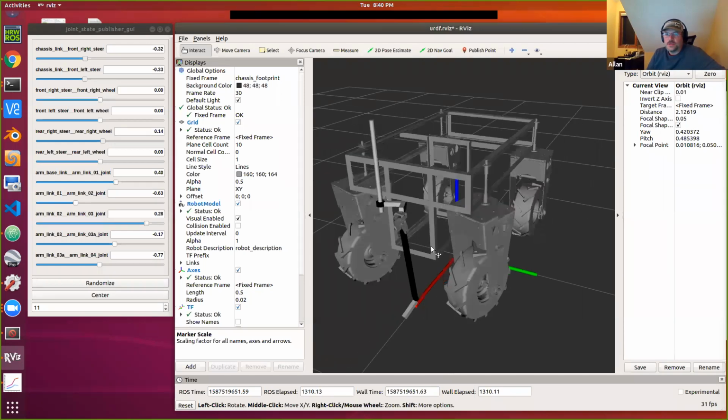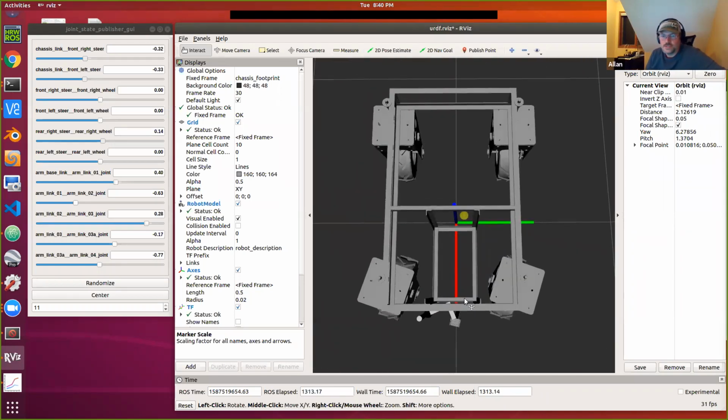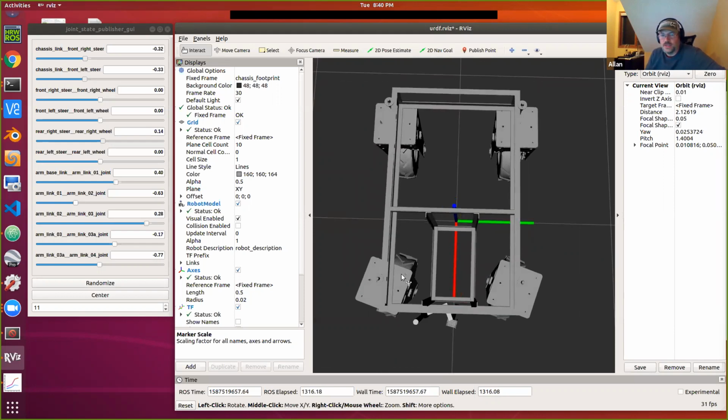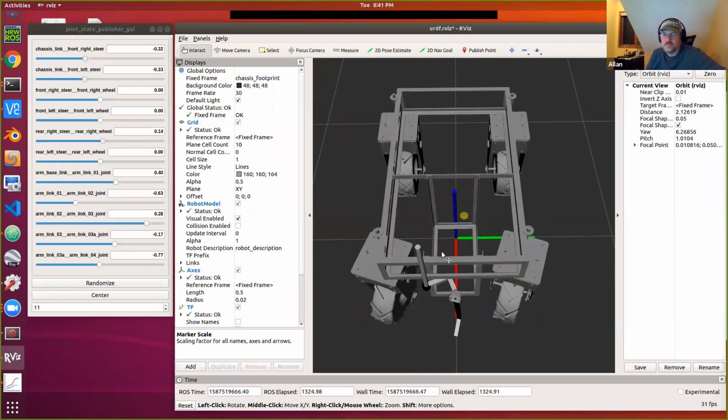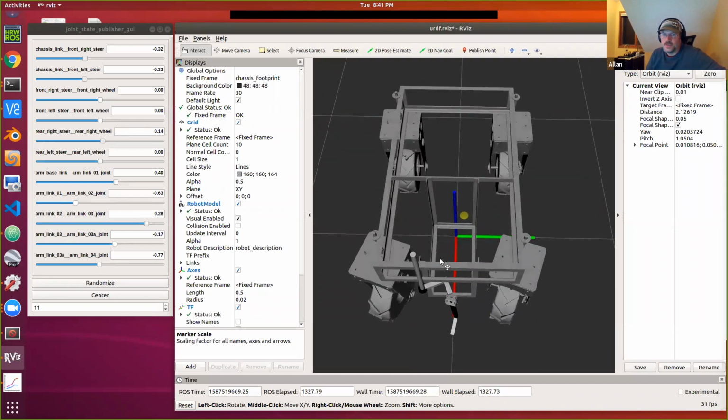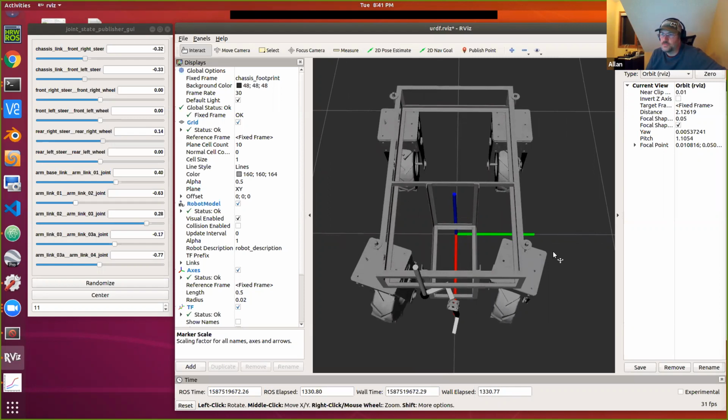Yeah, and in the actual rover, I don't have a physical link that goes between the two front steering mechanisms. They're completely servo motor driven on each side, and then I just set the angles accordingly. So I'm not driving both with one servo, but the same concept, the same angles apply. You have to have the same angles, whether there's a linkage in here or not, in order to have good turns.